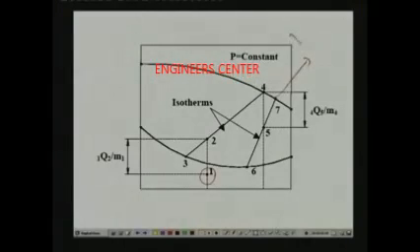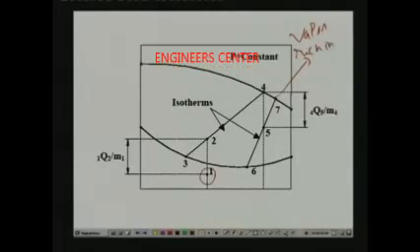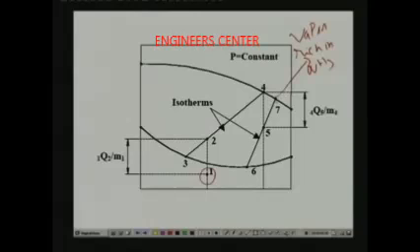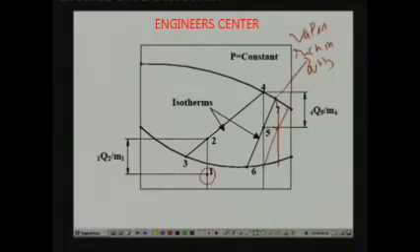Okay, we have taken subcooled liquid at this point, and we are getting a vapor that is rich in ammonia. Suppose this process is continued further. You will find that you have taken this vapor again and cooled it, and you have separated out the liquid and vapor again. So, you can see that this point, that means the outlet point, progressively moves closer to the pure ammonia state. That means you are getting vapor that is rich in ammonia at the exit of this arrangement.